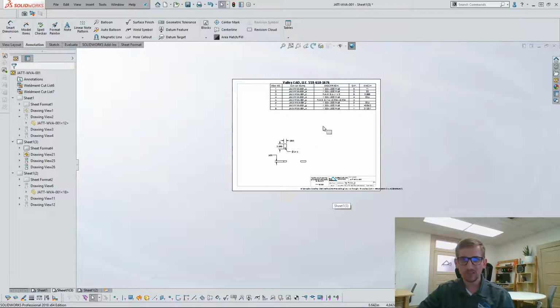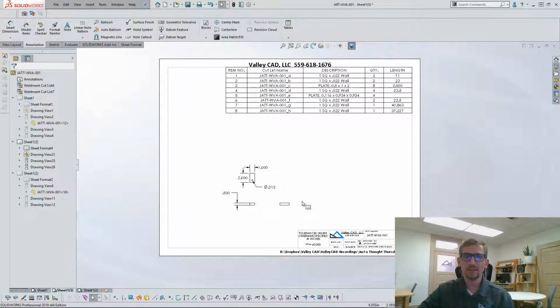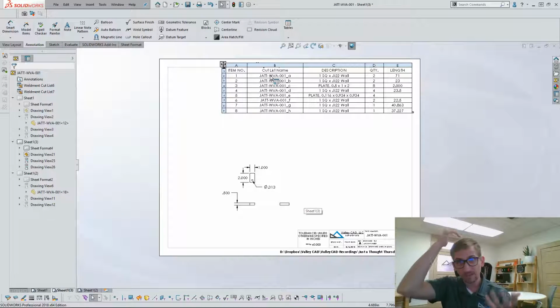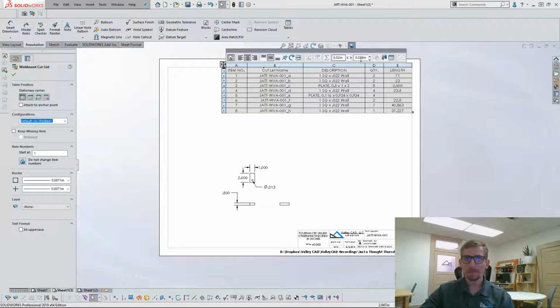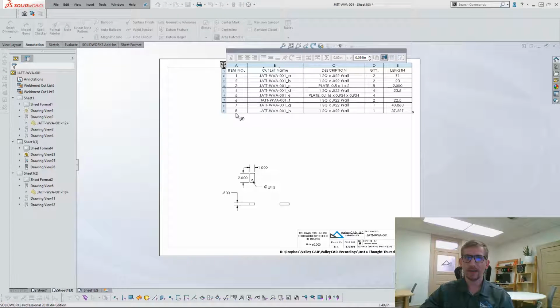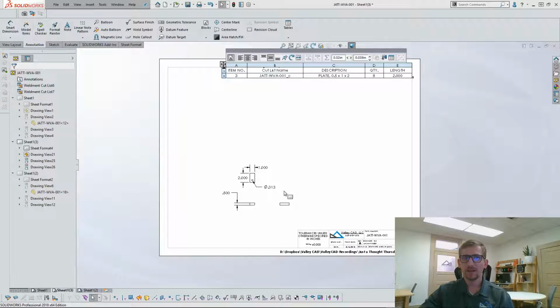Now you might be looking at this going, all right, Peter, great, you got this on there. Now I see all these items in my cut list. My guys on the shop floor are going to get confused by this. Not to worry. What I would do is simply come in and say hide items. By clicking on that eyeball and clicking on these numbers on the far left of your cut list table, you can simply say hide those items.